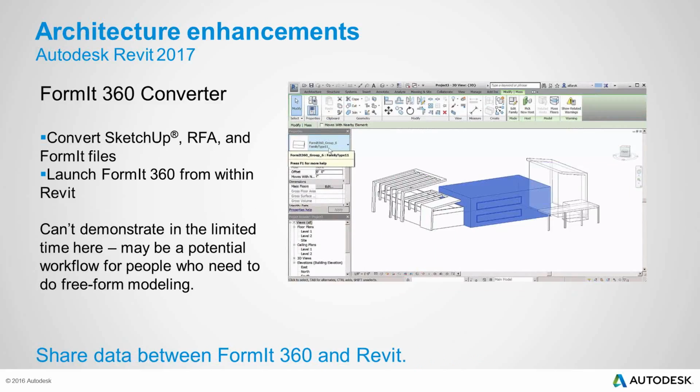Some of the things I won't be actually looking at in the demonstration is this thing called Formit 360, which is a web-based sort of SketchUp style environment where you can do free-form modeling. So what they've done is they're still working on Formit 360, and they're creating a workflow now where you can go from Formit and turn it into a Revit family and bring it into the project, and vice versa. So you can go from Revit and bring it out into Formit and then manipulate the object.